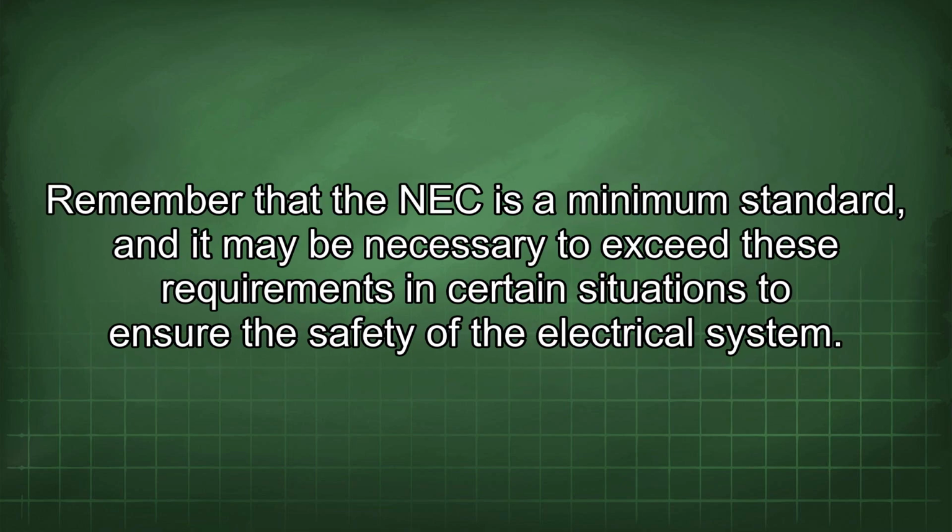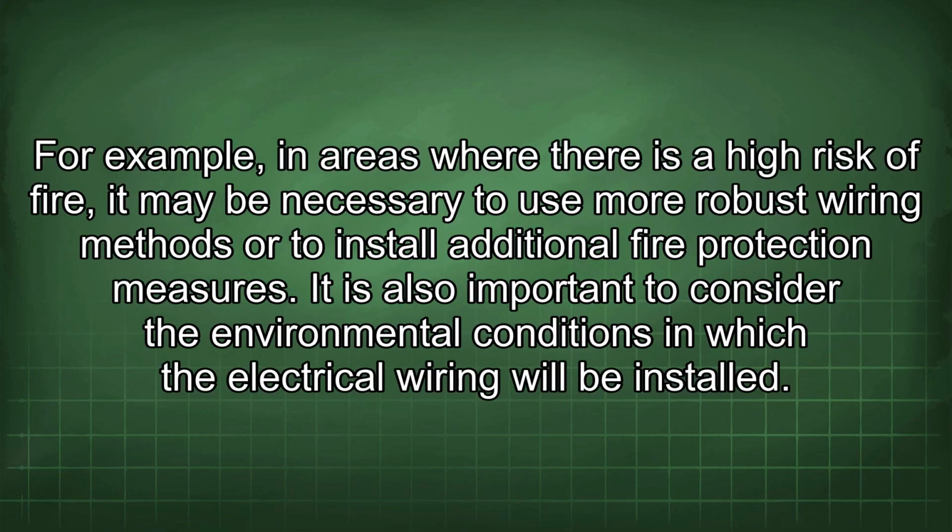Remember that the NEC is a minimum standard, and it may be necessary to exceed these requirements in certain situations to ensure the safety of the electrical system. For example, in areas where there is a high risk of fire, it may be necessary to use more robust wiring methods or to install additional fire protection measures.